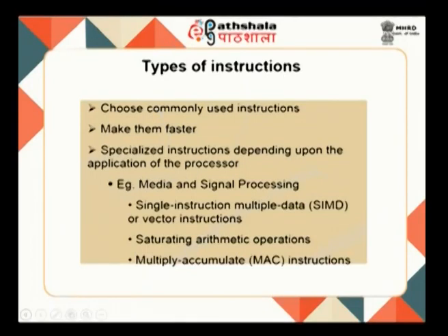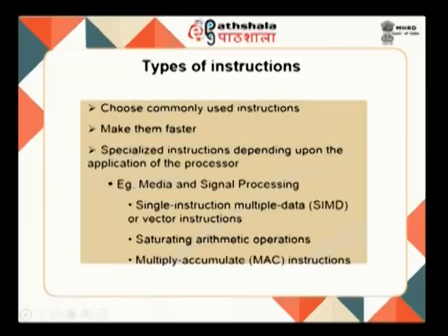So, examples of specialized instructions may be media and signal processing. When you are looking at media and signal processing, you may have to bring in SIMD type or vector type of instructions which try to exploit the data level parallelism, where the same operation of addition or subtraction is going to be done on different types of data. And then you may have to look at saturating arithmetic operations, you may have to look at multiply and accumulate instructions. So, you either look at a general instruction set or you also include some specialized instructions based on the applications that you are targeting.